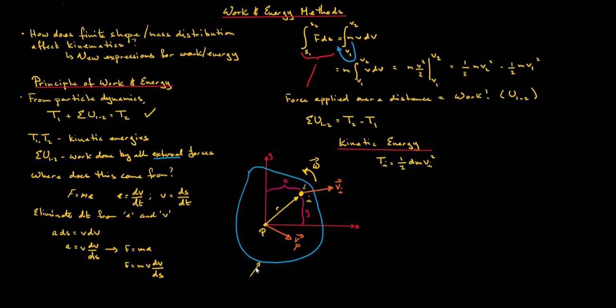Okay, so we can imagine that for the entire rigid body, it will just be a summation of all the individual kinetic energies. So we could say that this is equal to 1/2 the integral of dm v_i squared. And so this is for the entire rigid body, where an integration, as you know, is simply a continuous summation. Okay, so we need to define this v_i.